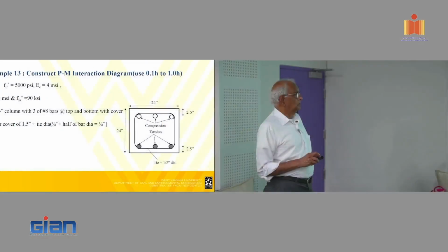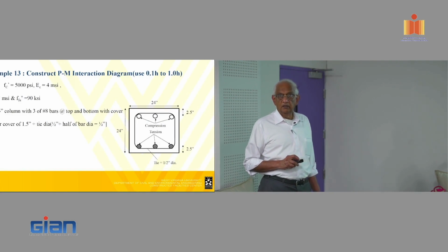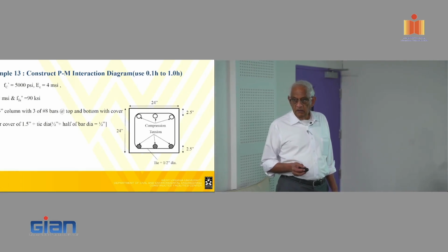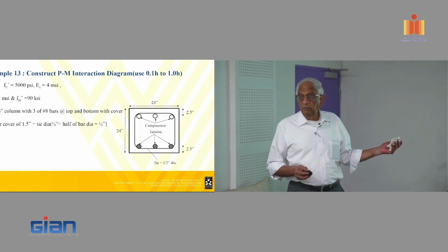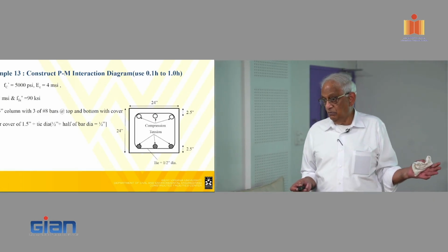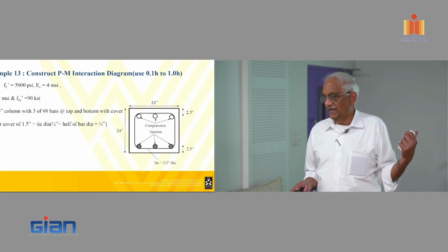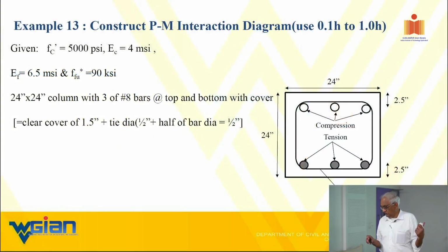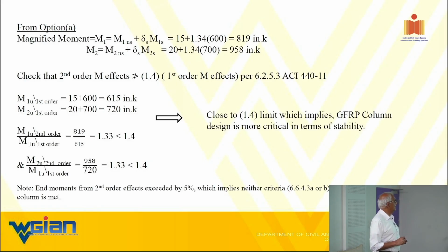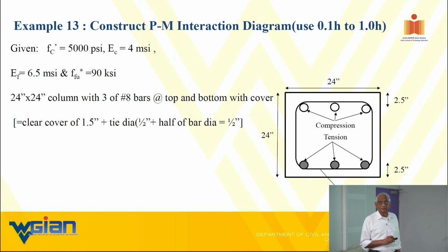So we're talking about the P delta effect for a column, 24 by 24. That's what we got, if you remember, right? So now I have a size of the column. I have the P values and the moment values. The question is, will the 24 one satisfy those numbers I gave you in the earlier slide? What is the number I need? I need to make sure whether or not this is going to satisfy the design. Right? That's how it goes.